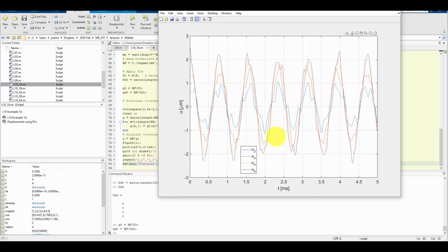So keep in mind before we compare this to when we solve this analytically, that right now our solutions are based only on 4 natural frequencies, and we already know that the 4 natural frequencies that we found all have error in them, a good amount of error compared to what we know they should be. So the natural frequencies are certainly incorrect, and there's only 4 of them. When we plotted this with the analytic version, which I'll compare it to in a minute, we used many more natural frequencies when we were doing that summation to get that result.